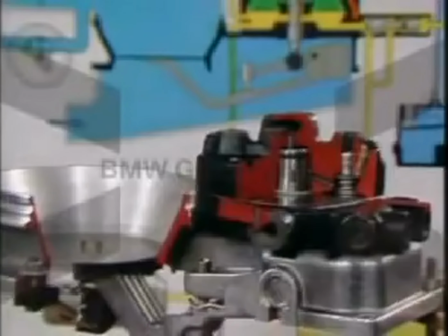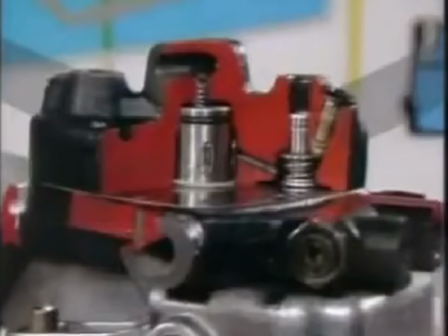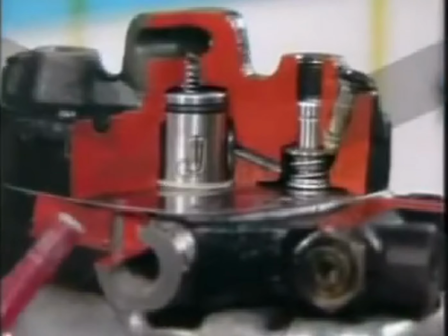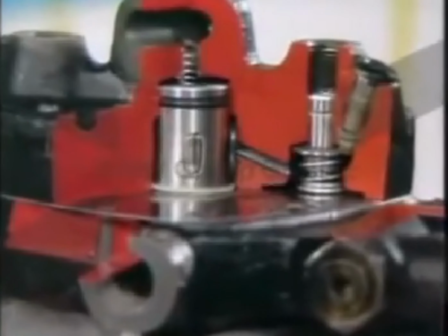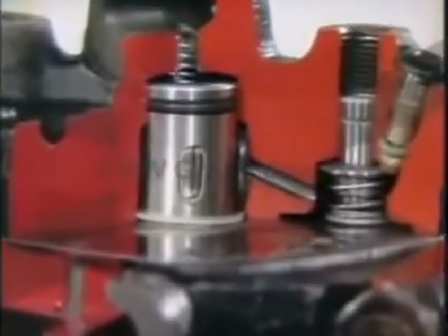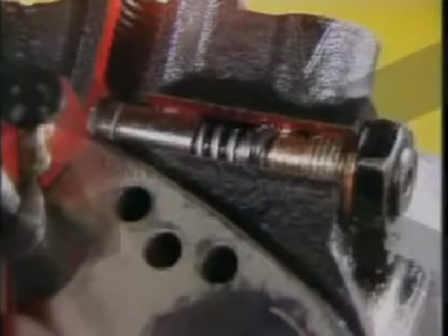The fuel distributor consists of the following parts: the upper and lower housing sections, the steel membrane which simultaneously separates and seals the two housing sections, the metering slit barrel with control plunger, the differential pressure valves, the primary pressure control and non-return valve.